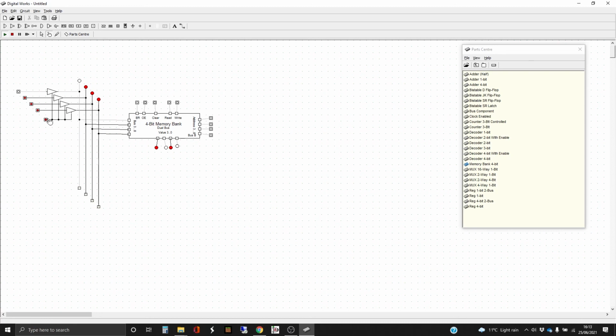And let's at this point check the output enabled to the bus. So let's disable that one. And it becomes a lot more pain when testing this if we're not careful to do that disabling, because stopping the simulation will get rid of the values that we've got in the memory. So output enable 10. There we go. And we're going to go to location 0001, and we're going to do a read from there as well. And that's the 7 that we put in earlier. And then if we do output enable, that puts the 7 on the bus.